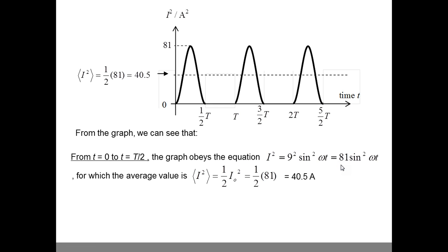And after squaring it, the root mean square current, the activities you need to do is to square it, to mean it, and then to root it. So to mean this part provides another new difficulty for us. Previously, if all the other waves were still present, the mean square current is essentially the halfway point, half of the maximum value. Right, 40.5 is half of 81. I've done it by showing you that the areas on top match the areas below. So how do you find the mean value now when half of the wave has disappeared?